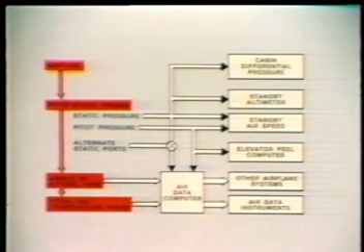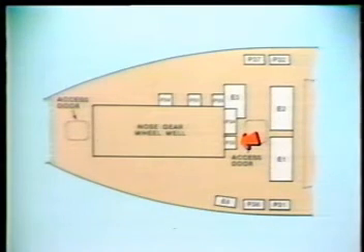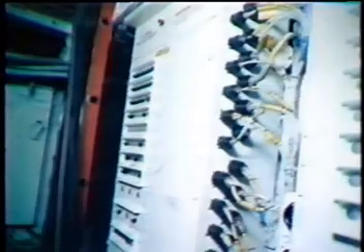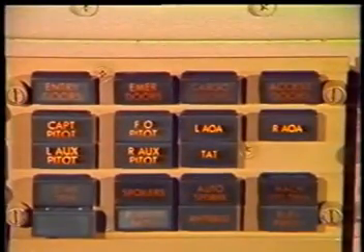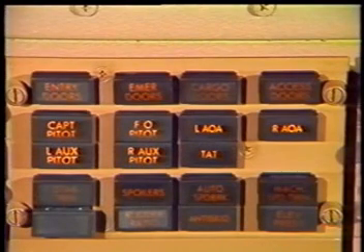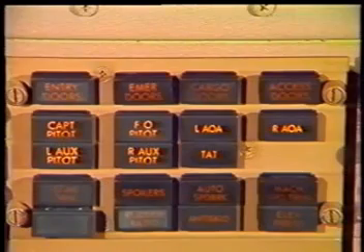Heating coils and control circuits prevent icing of the pitot-static probes, angle of attack sensors, and the total air temperature probes. Automatic controls for the heater coils are located on the P33 panel in the main equipment center. Probe and sensor heat controls are automatic upon engine start. A fault within the system will illuminate amber annunciator lights on the P5 panel, and a message will appear on the maintenance display of ICAS.